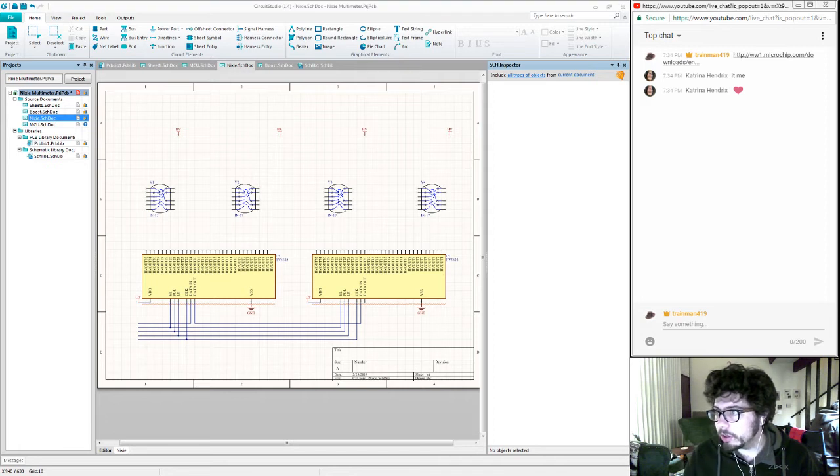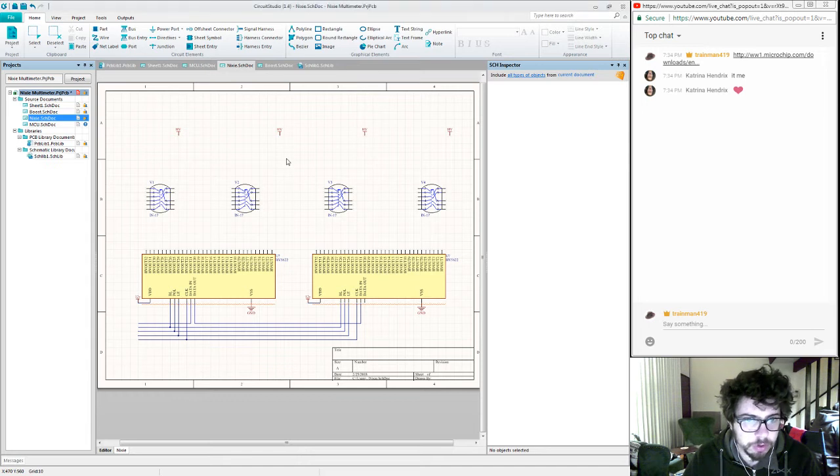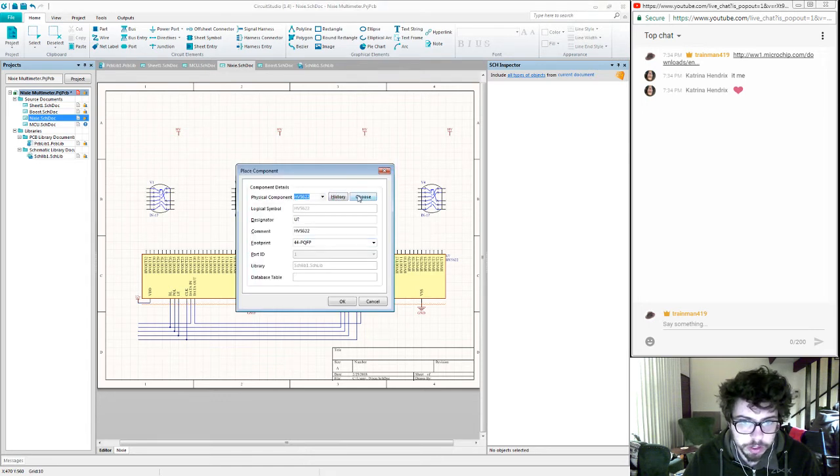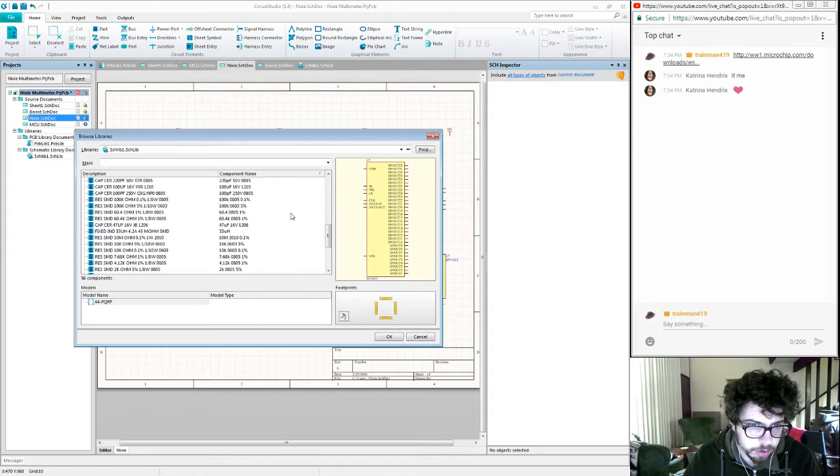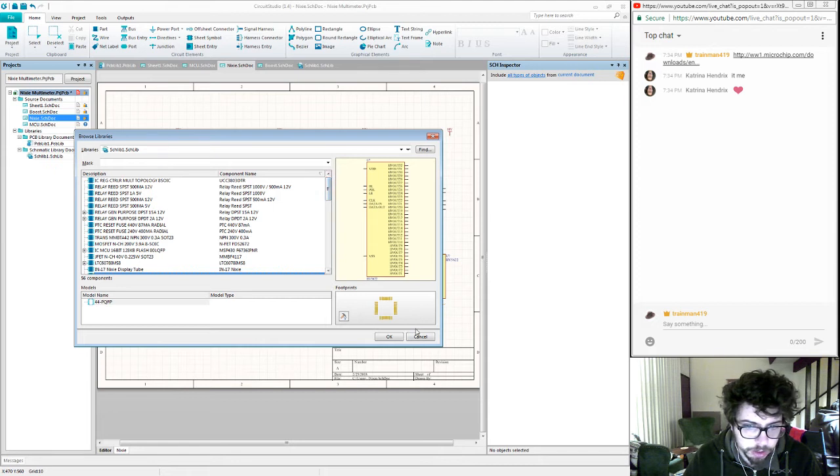If I go and look, let's see, where did my data sheet go for the Nixie tubes? They say a 30 kilo ohm resistor if you're driving from the minimum of 200 volts. Do I have a 30K resistor? I have a funny feeling I don't have one in my component library yet. That will have to come later.